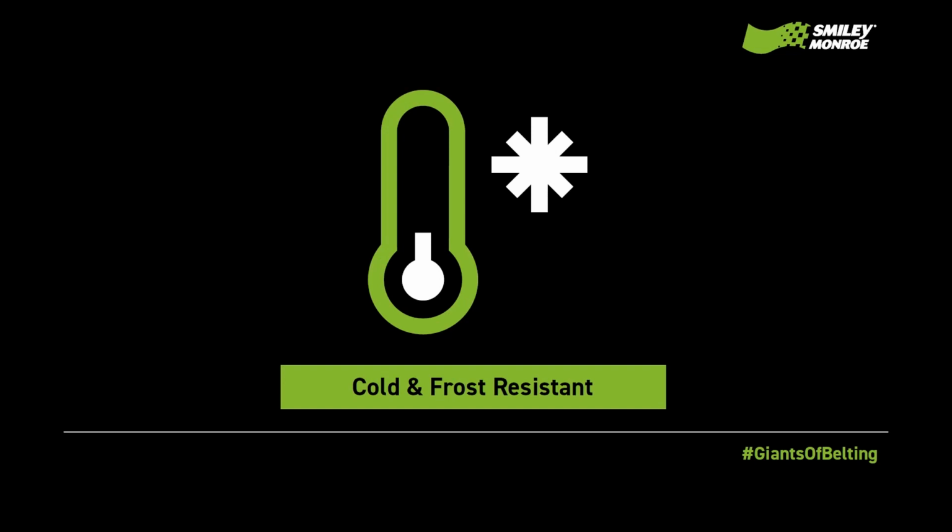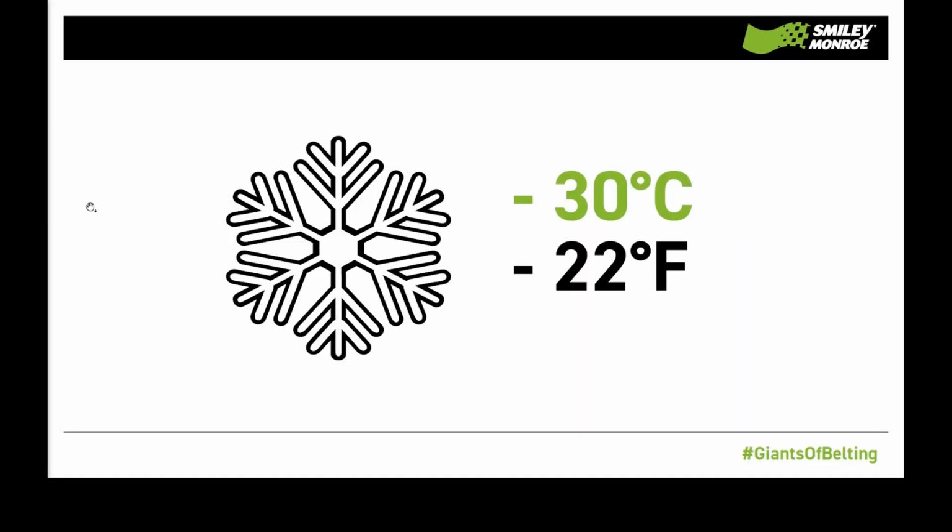Cold resistant belts are manufactured to DIN and are suitable for minus 30 degrees Celsius or minus 22 degrees Fahrenheit. It is extremely important to use cold resistant belts in these temperatures, as otherwise the belt will freeze and become difficult to track and trough. Low temperatures can do serious damage to the actual conveyor belt carcass itself. Choosing the correct thickness of the cover is essential because the cover acts as a barrier between the cold source and the carcass.